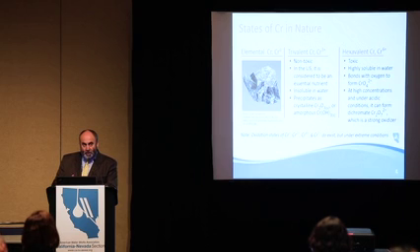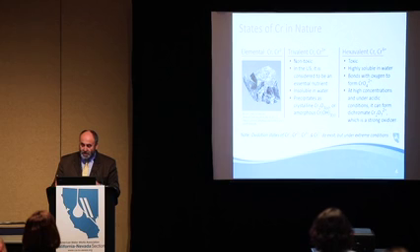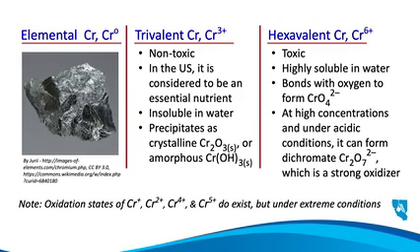What is also important for treatment purposes is to recognize that while as an ion it is positively charged, if it's in water, it binds with oxygen immediately and generates a negatively charged ion. That is the CrO4 that you see up there. So when we talk about Chrome 6 in water, it's pretty much all CrO4, a negatively charged ion with a divalent negative charge.